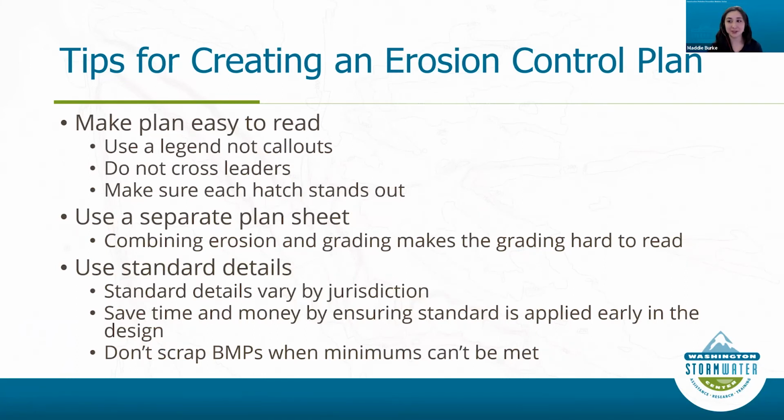And then Jordan mentioned this, you always want to use your local jurisdiction standard details. So these details do vary by jurisdiction. You don't want to guess. You don't want to say just because Clark County is really close to Vancouver, they're probably the same. You want to look and see what specific area you're working in and what standard details they require. And you will save time and money by applying these early into the design.